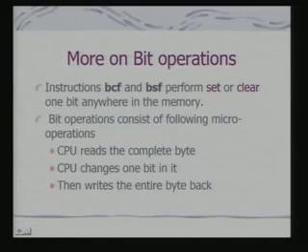Obviously, the issue that comes up is that when you are reading data from an external port and modifying it, this modification requires a finite time period. During that period, if there is a change in the input, because you are reading the data from the port input pin from the external source, what happens? We shall discuss this problem when we discuss the peripherals, that is, the digital I/O ports supported on PIC. But this read, modify, write is again an atomic operation.